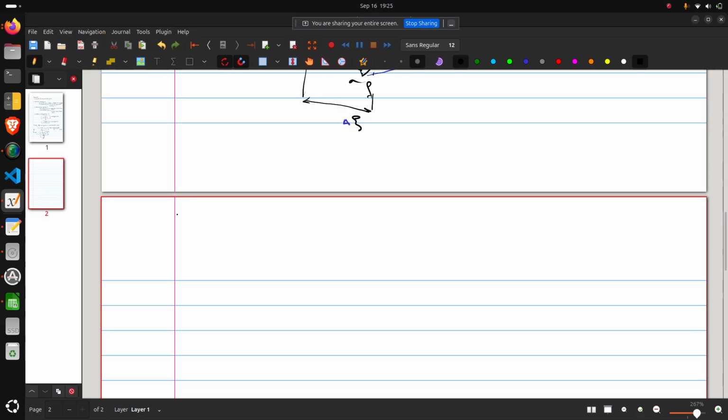So we have gamma times gradient of phi at the face, which is nothing but gamma at face f times i cap dou phi dou x plus j cap dou phi dou y.